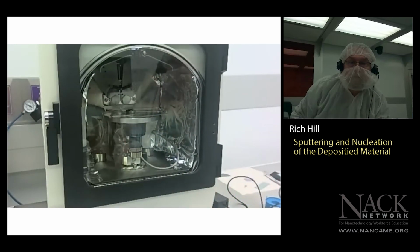So it's doing a purge cycle to get us nice and clean in there and mix our gas up a little for us so that when we get started, the pressure will drop to where it needs to be. And then the pressure will give us our plasma, as you guys have been talking about, and we will be sputtering our gold.